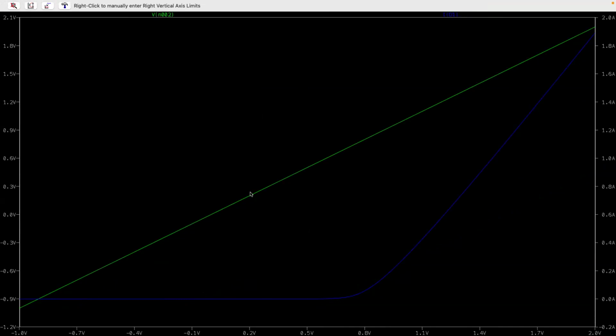And then from here back, you can't read these axes. This is 0 volts. Behind here is negative voltage across that diode. So like I was saying, you can't pass current in this direction through the diode. And then from here to here, before you start that curve, I don't really remember what they call that region, but essentially the diode just doesn't have enough voltage across it to begin passing current through it.